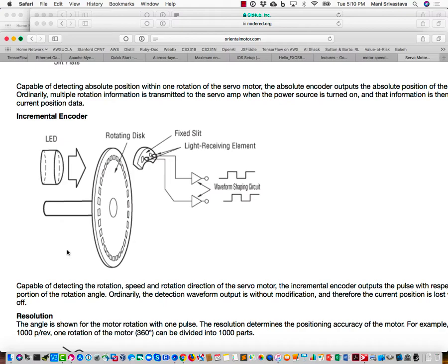When the motor is rotating, the waveform that comes out here has a frequency that corresponds to the frequency at which the motor is rotating. And I can measure these things. So it's not PWM, it's pulse frequency modulation instead of pulse width modulation, but the same concept. So what comes out of the motor in the form of the speed is this kind of a waveform. And now in the reverse direction, using your timers and the MCU, you can measure the speed of the motor.